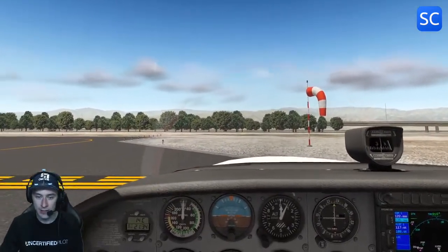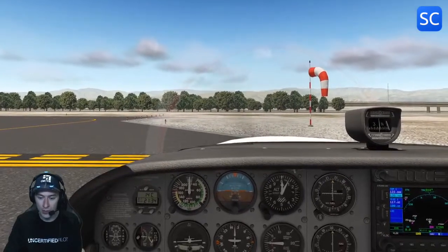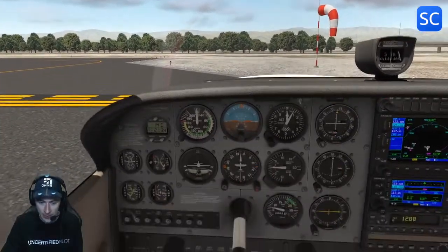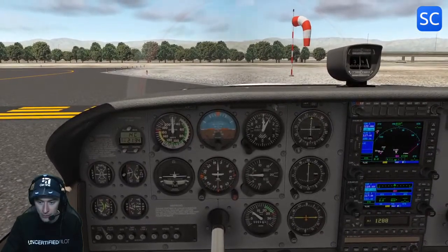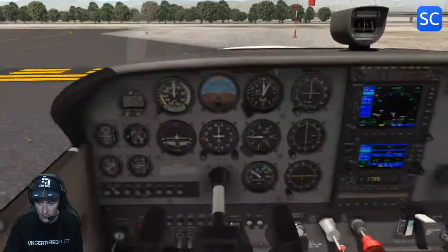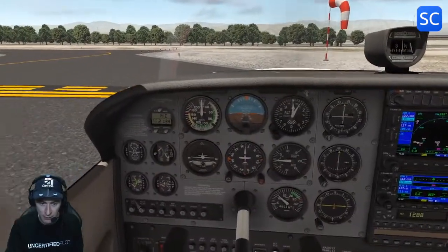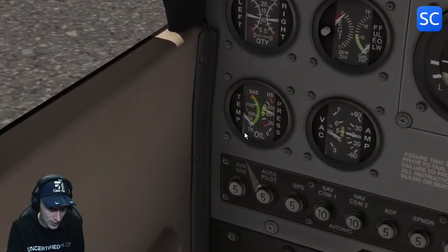Well, I think this is fine. We don't have a significant wind, so usually you would point your nose into the wind so it cools the engine while we do our run-up. Again, setting it to 1000, but let's set it to 1200, so we foster that warming up process. Engine is still leaned, that's perfect, but you can see the oil temperature is not quite in the green.